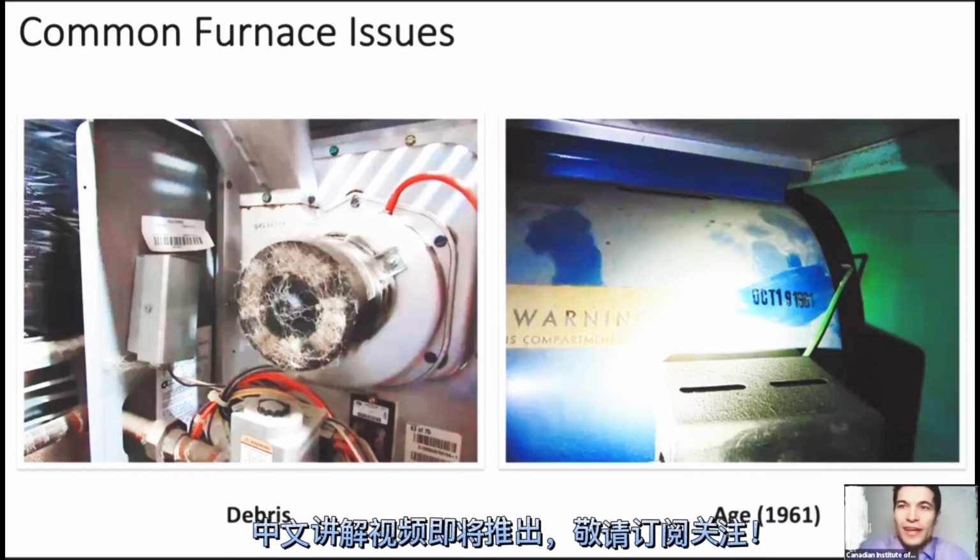Like Sam was saying, with newer furnaces and boilers, when the heat exchangers went from cast to stainless or composite materials, they're not built to last as long. Some inspectors choose certain time frames, like 20 or 25 years. Some might push it to 30 years, but figure out a date you're comfortable with. If a furnace is 25 years old, you might recommend that it be budgeted for replacement.